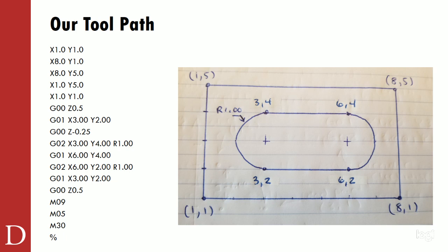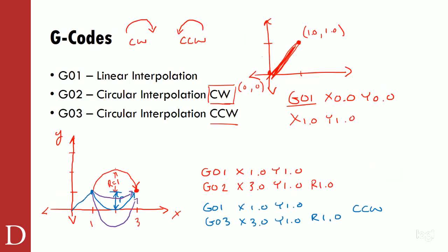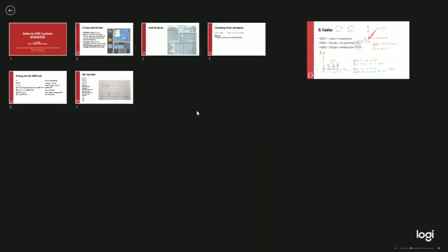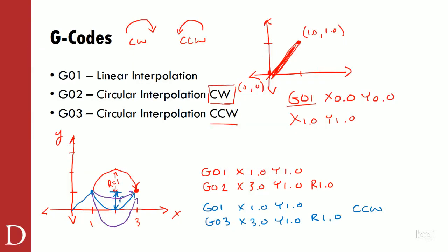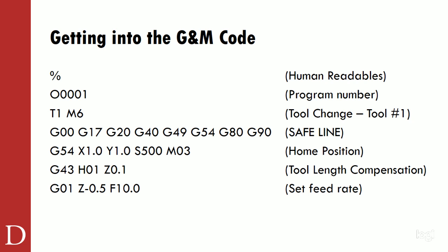And I do want to go back for a second on this here, because even on some of these, it may be required to actually redefine, where did I go there? There we go. You may notice when you're creating programs like this, you may actually have to define intermediate points. This curve's real simple, but this curve is a little bit more complex, and there may be intermediate points that define radius in between those parts of the arc as well. So I don't want to make it as simple as I maybe laid it out there.